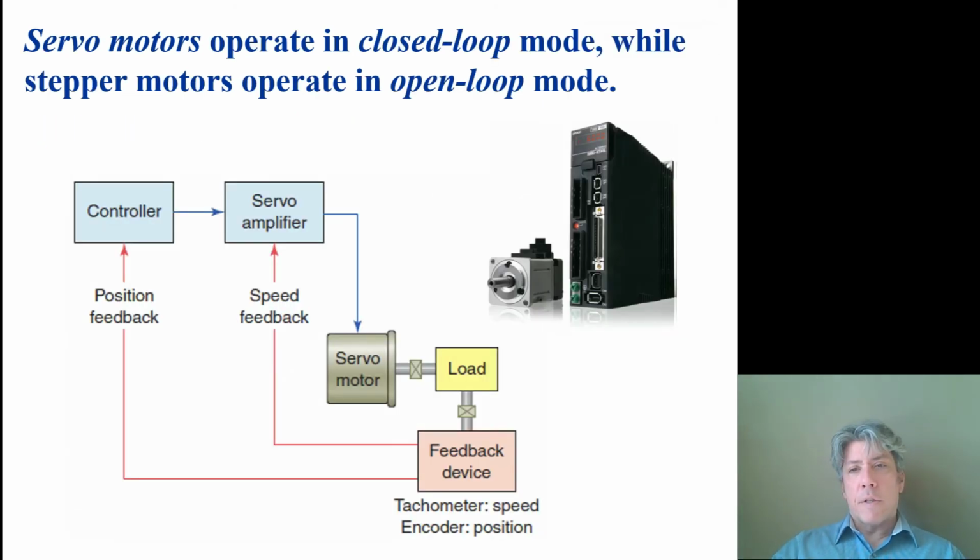Servo motors are a little bit different. A servo motor might look a lot like a stepper motor, but you'll see that they look different. The way they usually operate, I don't want to say these are always DC motors, but they are frequently DC motors. A servo motor has some type of feedback, whether it's an encoder mounted on the back of the motor shaft or some other type of feedback. That feedback is used for determining the position of the motor shaft, and that way you can apply more power to the motor or less to try to get it to the desired position. So they're not stepper motors, but you can do some really good control with these if you have good feedback to get the motor to particular positions.